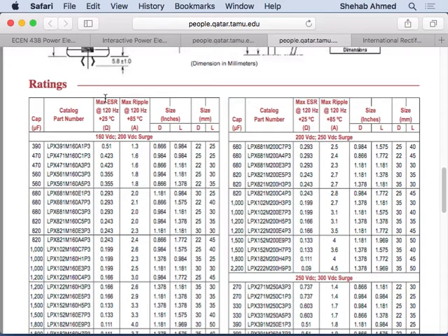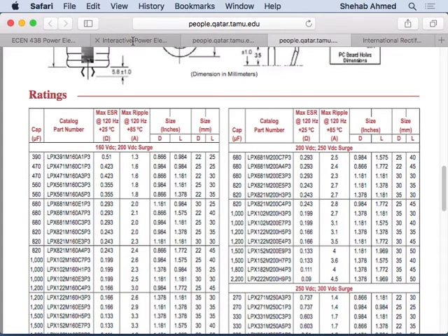Because again, this capacitor is a wound component. The equivalent circuit of the capacitor is not purely a C and a resistor in series. Some equivalent circuits will include inductors and parallel combinations, and they would have some funky characteristics, and these all depend on the value of frequency.